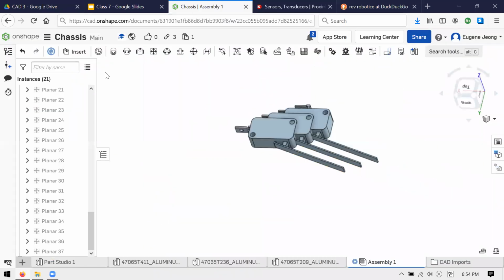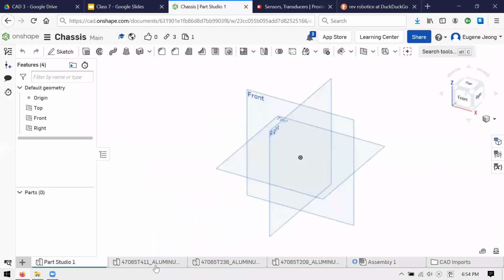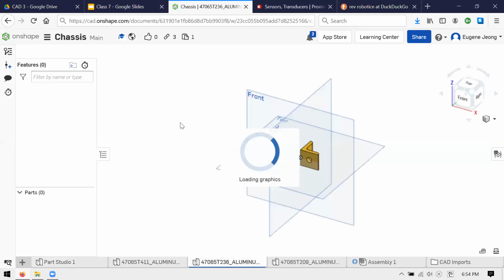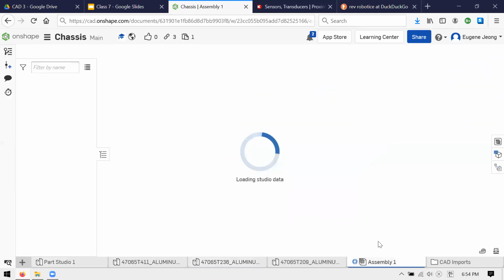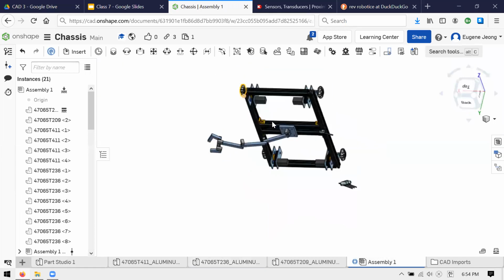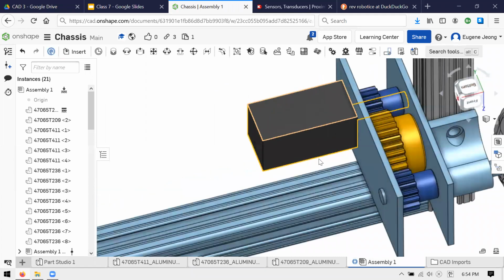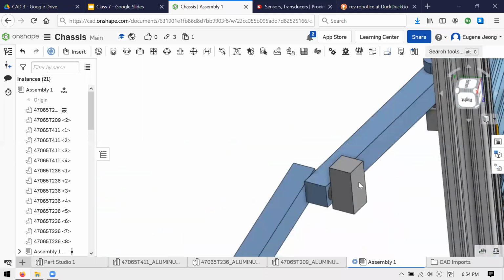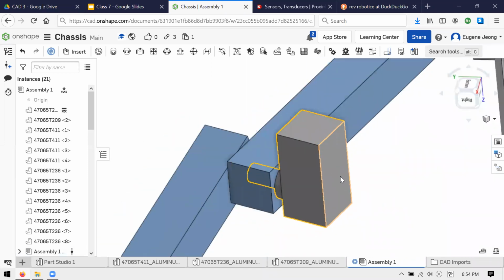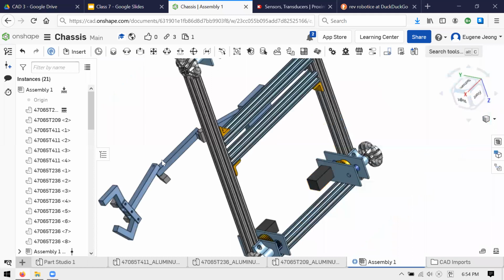And so in those cases, what you can do is just like we did when we were modeling the arm and the gearboxes, you can just look at the part yourself and make a standard model, like we did here for the motor or here for all of these servos. What you should always ask yourself is, do I need an accurate model of this?